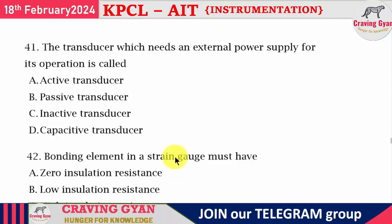Now this question is from transducers. So if you are in a position to justify what you mean by transducer and the types of transducer, that is more than enough in order to solve this problem. The transducer which needs an external power supply for its operation is referred to as a passive transducer. Which does not require an external power supply is referred to as an active transducer. A transducer is the one which is going to convert a non-electrical signal to an electrical signal. That's it.